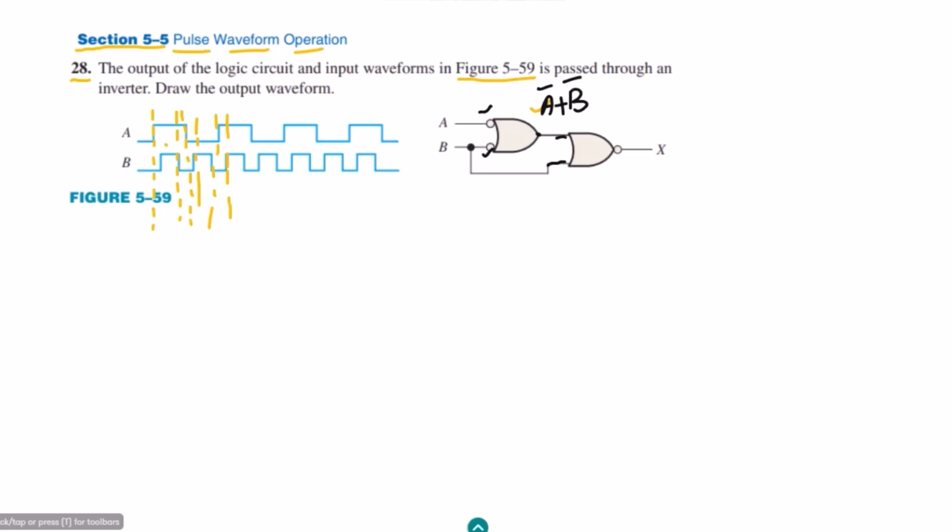to this second NOR gate, and at the output of it, what would we get? We would get A complement plus B complement. This is the first input, then OR of the second, and as this is a NOR operation, here it will be complemented. So here we have two inputs, A and B, and a single output, which is A complement plus B complement plus B, and the whole complement.